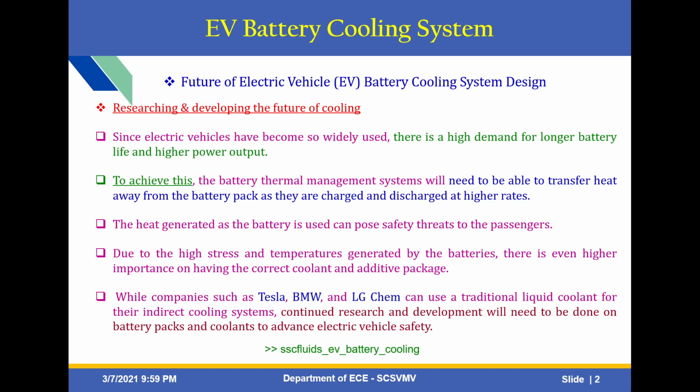Okay, for this example, we can get it from the command prompt. Just type the following keyword: ssc_fluids EV battery cooling. Otherwise, I will give the Simulink model in my YouTube channel description box. Kindly download it. You can check the EV battery cooling system design.